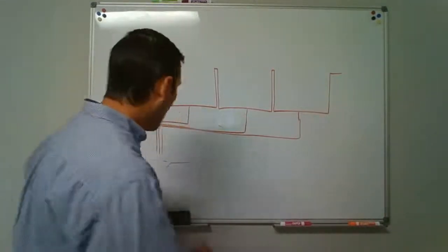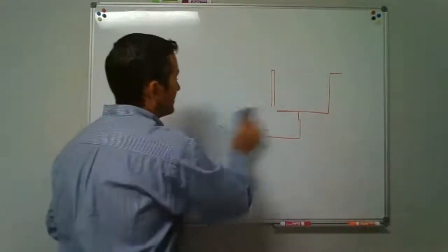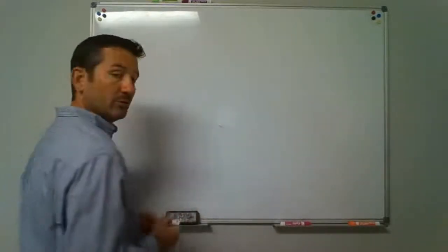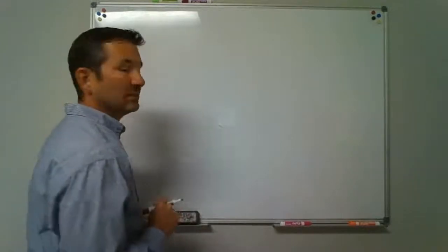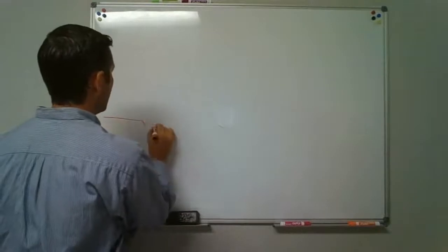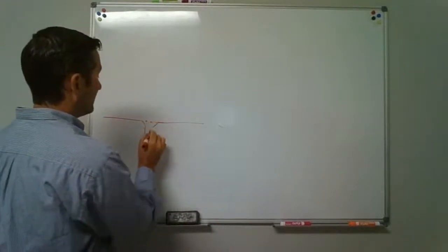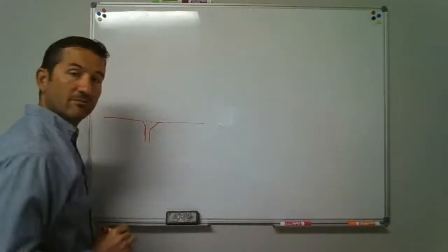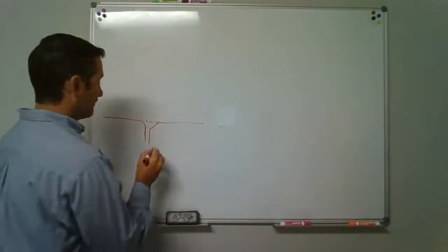Okay, so you got a big walk-in cooler, freezer, whatever, storage of food. You might want to be able to wash that thing out and clean it down. You get stuff leaking out from bottles and everything else, but you got this big walk-in thing with some type of floor drain there. But now, if it's in a place where it's going to be freezing, we wouldn't want to put a trap under there because that water is going to just freeze in there.